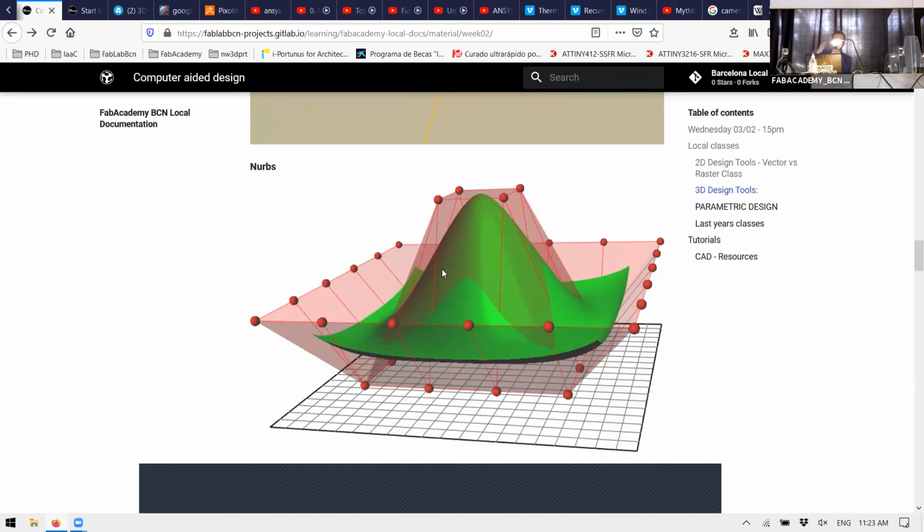We will do it by a cross-section of lines, because a cross-section of lines is way easier to define than a surface. So what we will do is we will take this control point, this control point, this control point, this control point, and the computer will interpolate. Interpolate is kind of average a curve between the different control points. Doing this in cross sections, one in X, one in Y, and one in Z, will give a matrix.